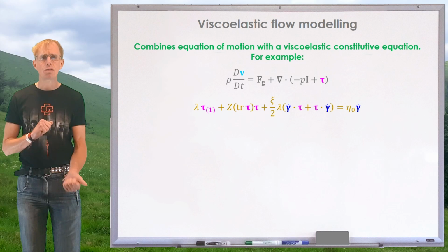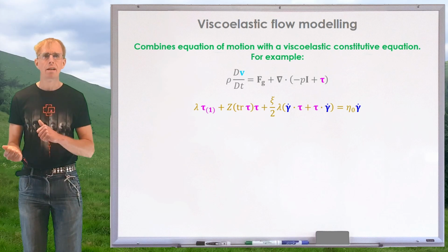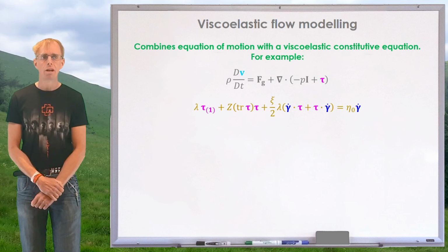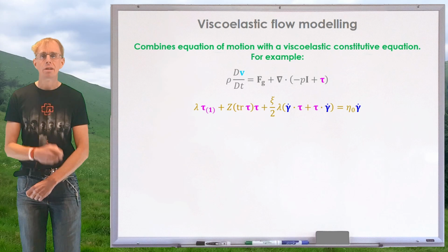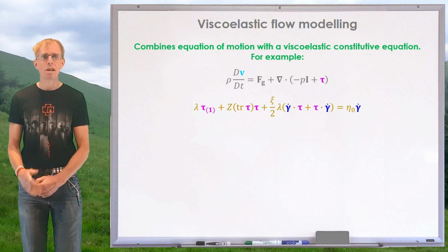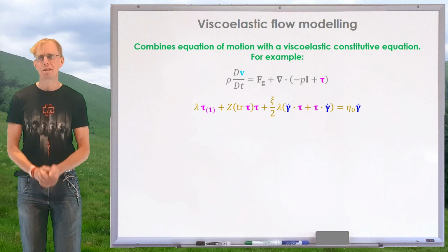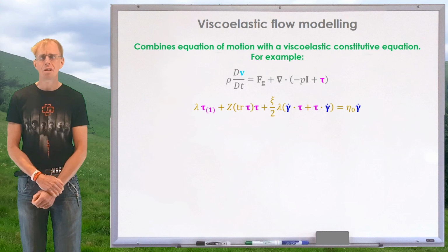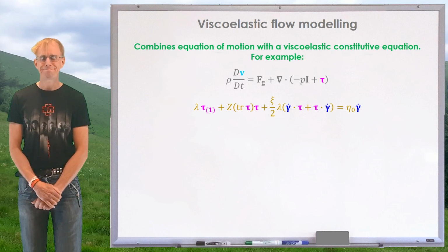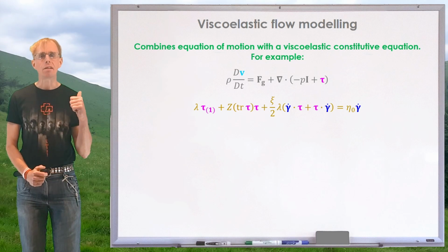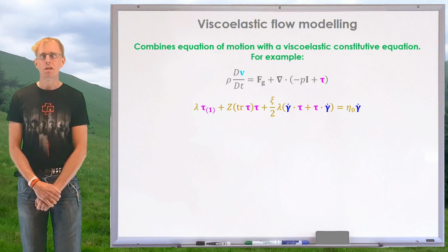Now, we need to close that equation and link stress and velocity field, and that is where our constitutive equation comes in. And ordinarily we'd say, oh, it's Newtonian, it's easy, tau equals eta gamma dot, and gamma dot is grad v plus grad v transpose. Now we're in the viscoelastic domain. So there on the board instead, I've put the PTT equation.